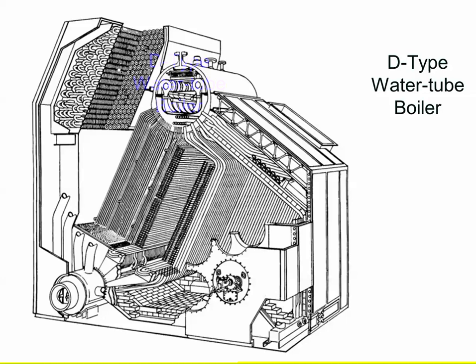Now, the reason this has been done is the compact high horsepower pumps, but also the fact that I can pull the flue gas off of this boiler, clean it by putting it through a scrubber, and use it as an inert gas in the cargo tanks to prevent explosions. So I can use the boiler to burn the oxygen, that 21% oxygen. It'll burn that oxygen down, typically at sea speeds out at sea, to about 2% oxygen in the updraft.